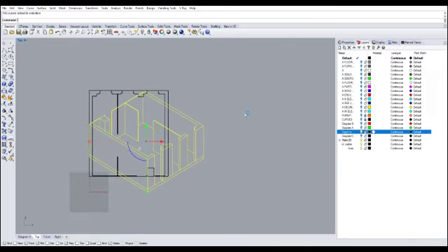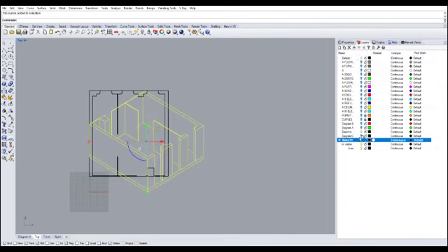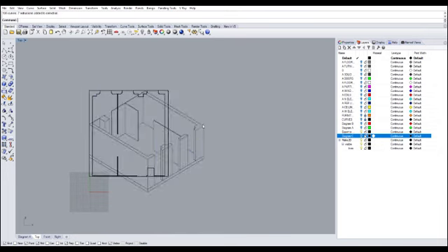So if you go back to your layers, we have some new layers here called Make 2D layer. Rhino makes this by default. I mean, obviously we can use this layer because everything just goes in there, but we don't want to do that. Let's go back to default as a current layer. We want to be consistent, so let's select our lines, just the lines.